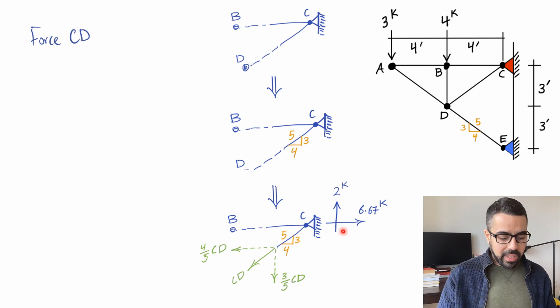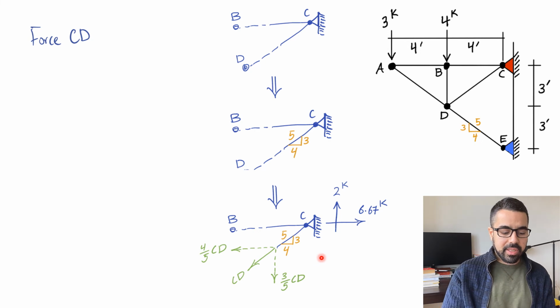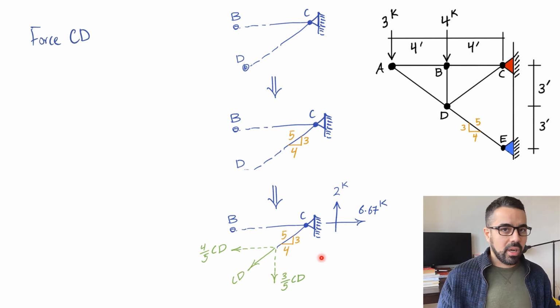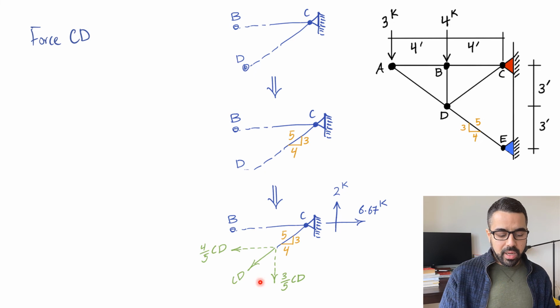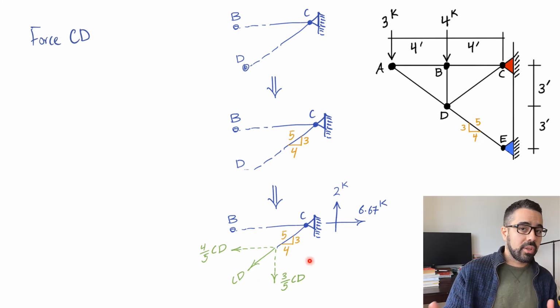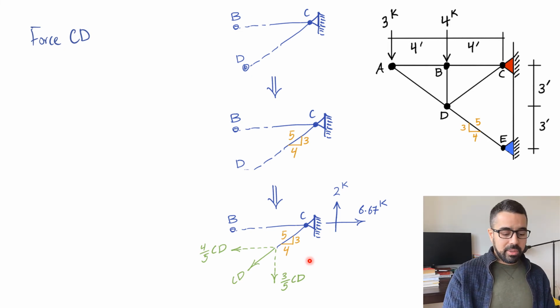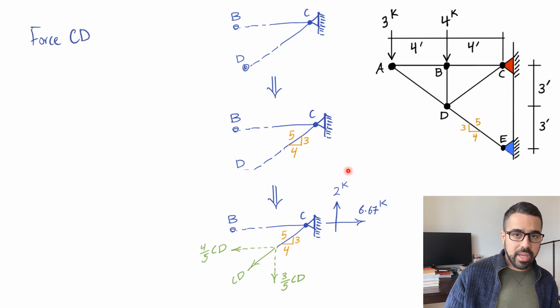So we have all the reactions, and now we can basically do summation Fx, summation Fy. Which one to choose? If I use summation Fx, again, we will have to find the member BC before we're able to find CD. So let's avoid summation Fx and go with summation Fy equals 0 because we have the vertical reaction. We found that a minute ago.